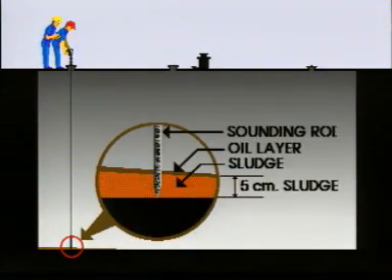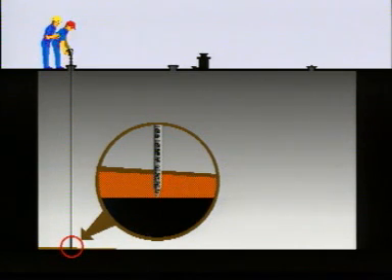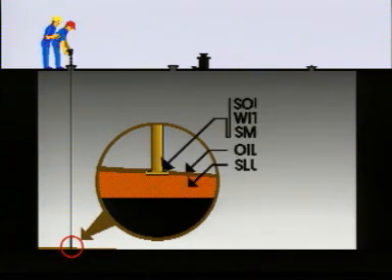Most likely there is unpumpable mud or sediment in the end of the tank. This layer may be penetrated and a thin layer of oil smears the rod. Your job is to prove that the findings are negligible, unpumpable, or out of reach of the vessel's pumps. It's a good idea to use a rod with a flat end to avoid penetrating the sediment.